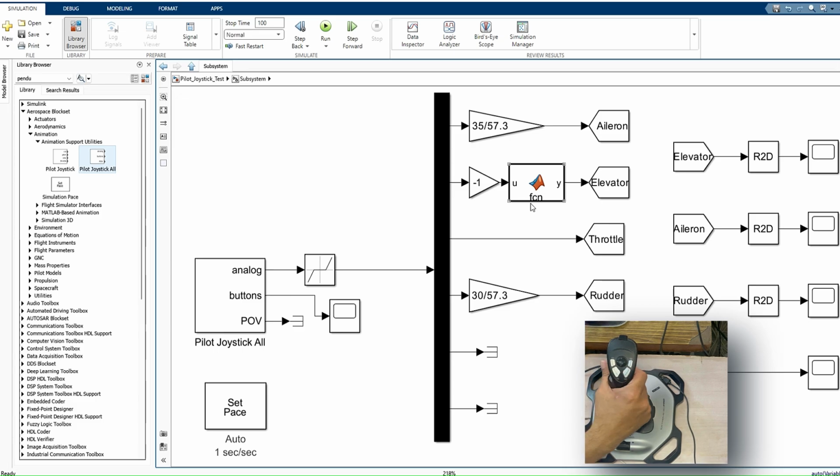Why is downward elevator deflection different compared to up? Because when you deflect down, the total angle of attack will be this deflected angle plus whatever angle of attack the aircraft is flying at. So there is a chance that you will stall the aircraft. The elevator gets stalled because the angle will be this angle plus the angle of attack, which can go beyond the stall. That is why you have a little less authority in downward than compared to upward.